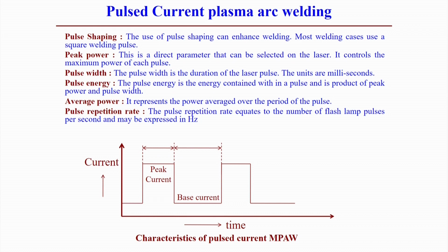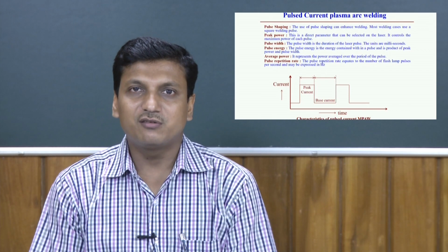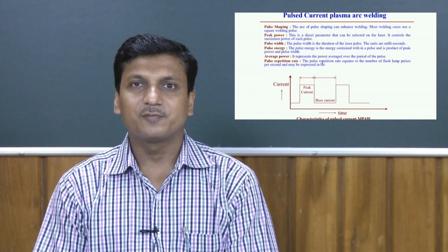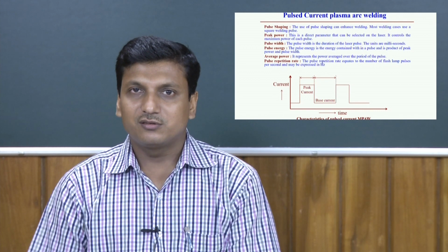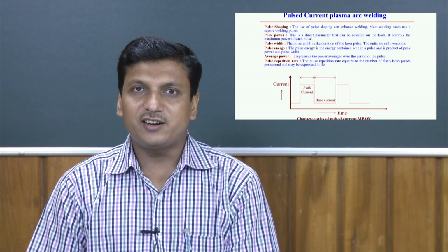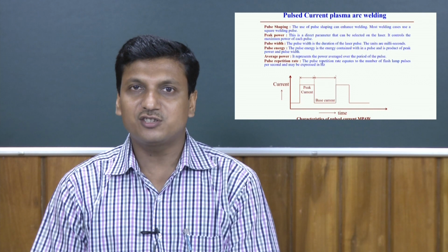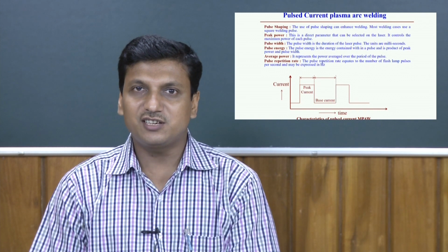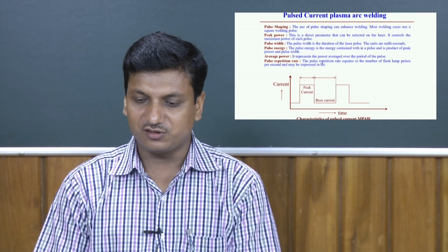The purpose of using pulsation even for plasma microwelding processes is that it helps to join very thin sheet applications. Basically, the ramping of the power in this case helps to join even much smaller thicknesses of material. That is the purpose of the pulsation even in the plasma microwelding process.